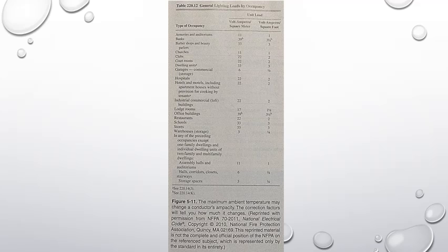Since the conductors will now pass through an attic with an ambient temperature of 125 degrees Fahrenheit, the ampacity will have to be divided by a correction factor to figure the new requirement. Based on Table 310.15(B)(2)(a), the correction factor is 0.76.